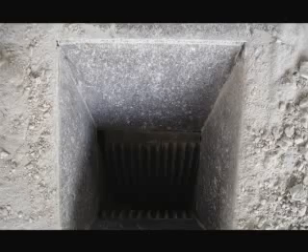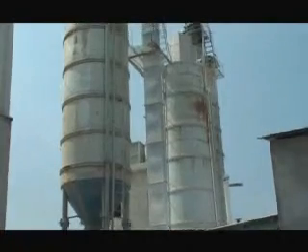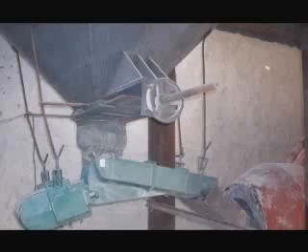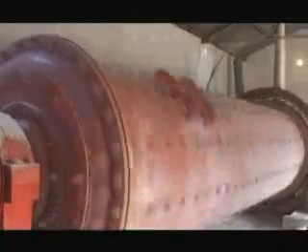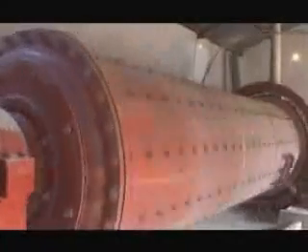After being crushed by the jaw crusher, lime is transferred to the crushed lime tank by the bucket elevator for storage. Then the electronic vibrating feeder under the tank transfers the crushed lime into the ball mill for grinding. The fine ground lime powder is conveyed to the lime powder tank in the dosing center by conveying system.